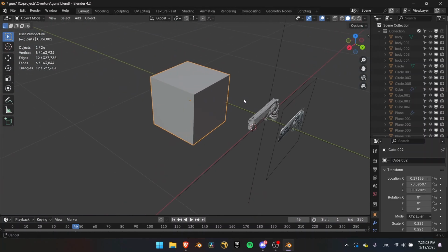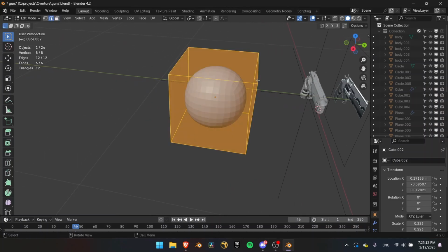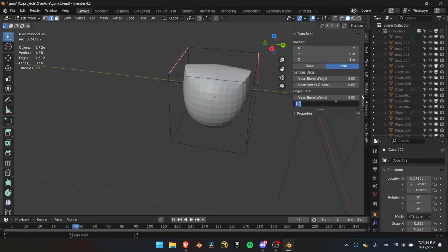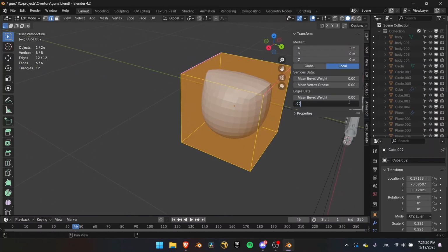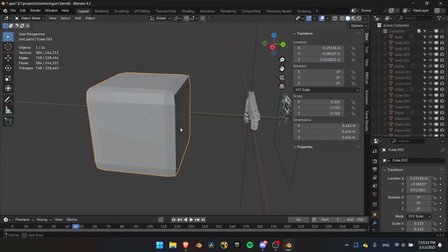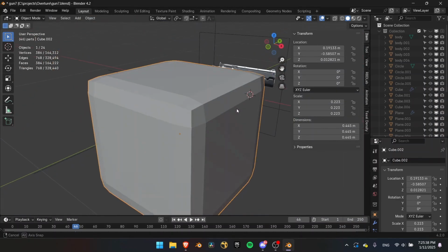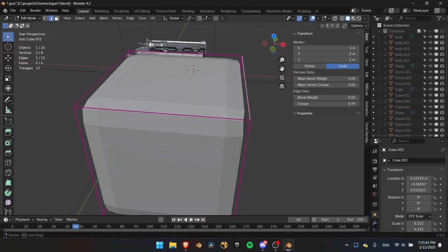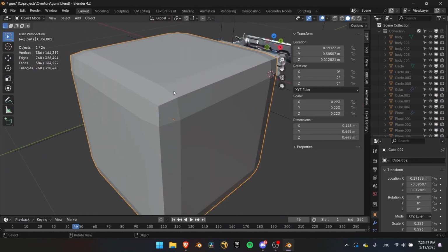The way I used to do these is I would subdivide maybe by 3, and then make these bevels by clicking those, and then turning up your crease by like 0.9, stuff like that. And if you do along the entire cube, you get a beveled cube, but it doesn't look really good. I guess it just directs the attention of where the edges of the subdivision should go. And so because of that, it's not very high quality.